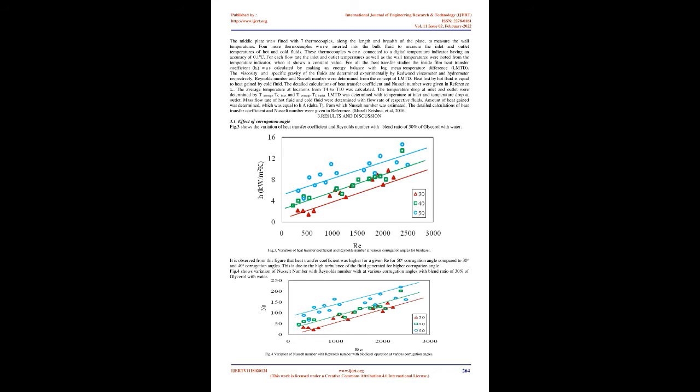Iulian Gherasim et al., 2009, calculated the fluid temperature profiles in a multi-passage PHE, and its effectiveness was calculated with a model which includes dissipation, temperature-dependent viscosity, and appropriate correlations for the Nusselt number and the friction coefficient. When the viscosity of the two fluids was low, e.g. water, the results were identical to the classic epsilon-NTU relations, which were obtained by neglecting dissipation and by assuming that fluid properties and heat transfer coefficients were constant.